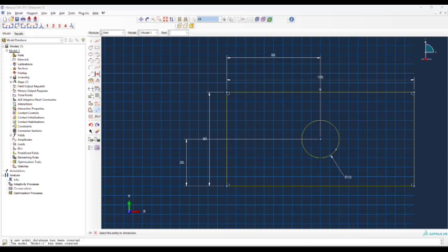Change units to millimeters. No, so it's not. So great question, Ethan. Abaqus isn't quite like SolidWorks where you have a unit system within it. Everything is kind of dimensionless and is prescribed up to you. So if I do this in 50, 100, etc., then in the material properties and whatever, I'm going to adjust accordingly such that it is in an SI unit in whatever dimensions you want. Does that make sense? You kind of have to keep track of your units on your own, which is a pitfall people can have, where if you make your dimensions too big in one length scale and then you don't pay attention to the loads or something, that could give you some trouble. So just be very careful with that.